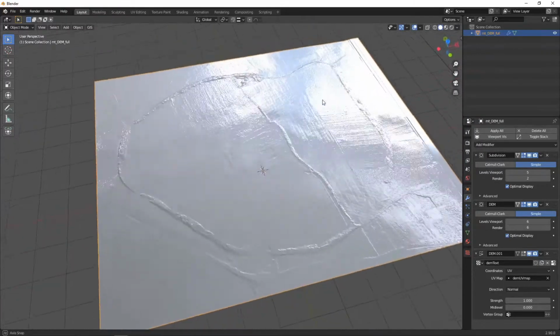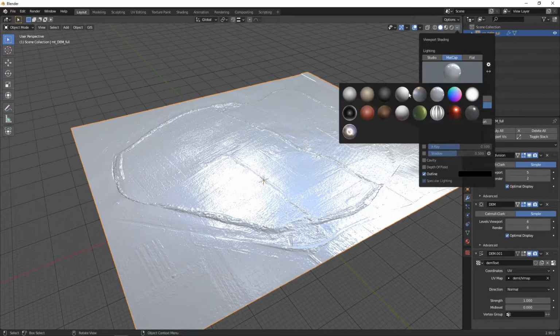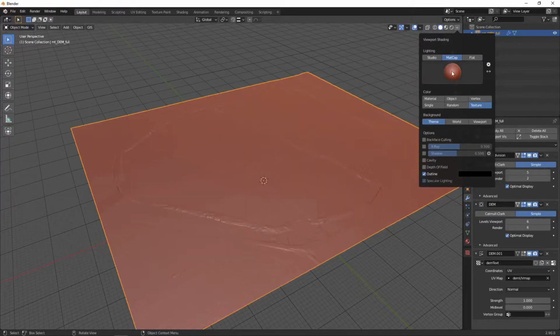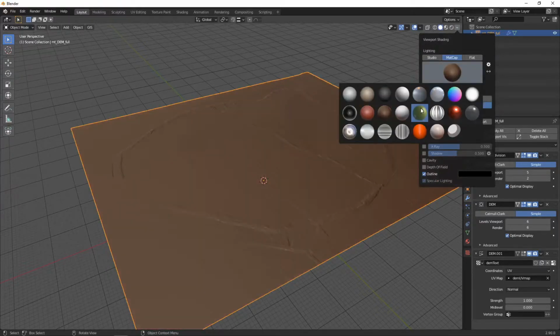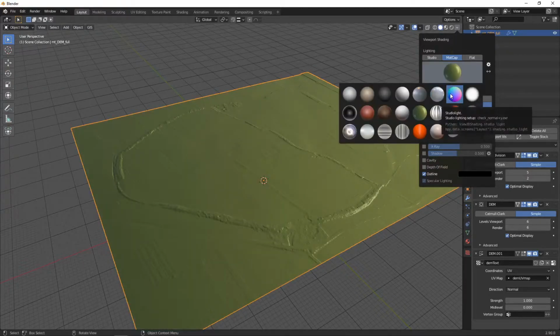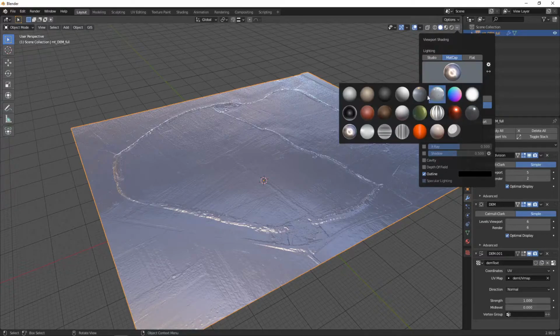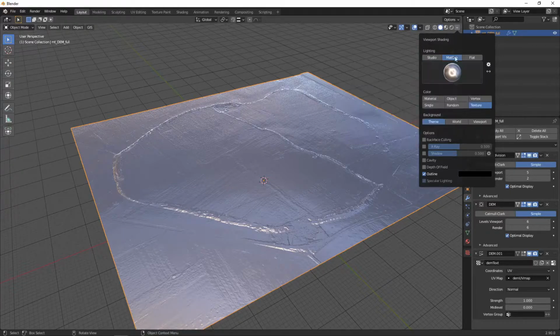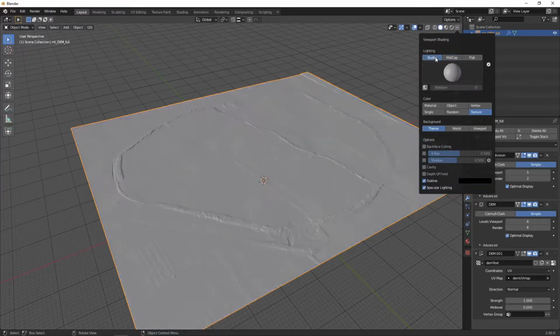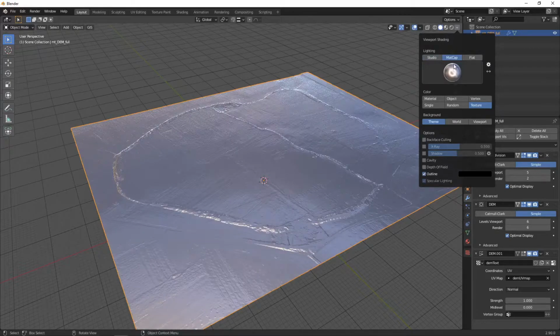Also the matcap one can be very useful. These are all used for modeling in order for the modelers to see their meshes better, and they can be used for us as well in a similar manner, because our aims are very similar to the modeler that wants to have a very good view on small details, mistakes, features of his or her models. So you can switch between studio lighting and so-called matcap, material capture lighting, and it gives you a whole range of options that you can explore.